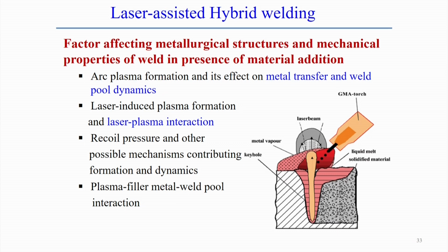First point is the formation of plasma, and of course, that plasma formation actually affects the metal transfer phenomena, and ultimately it affects the weld pool dynamics. Second point is that laser induced plasma formation and the laser plasma interaction become more complex in this case.